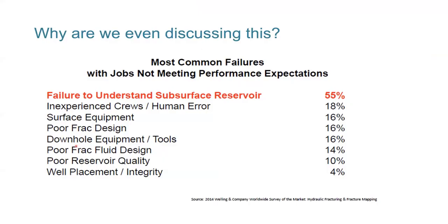I'd like to show this slide first to say, why should we all be talking about this? This slide is about hydraulic fracturing, as you can see at the bottom, but it's extremely relevant to anything in the reservoir, especially formation damage. It shows the most common reasons for jobs not meeting expectations. If there are drillers and completion people on the call, you'll be thinking well placement, design of the operations, or reservoir quality wasn't right.